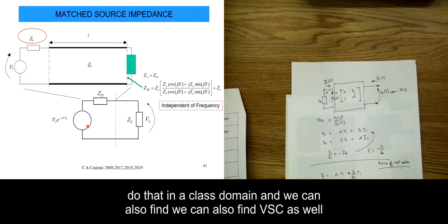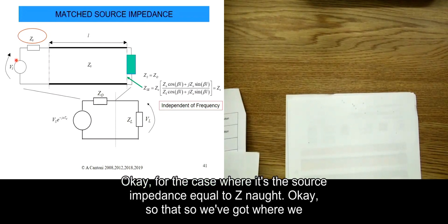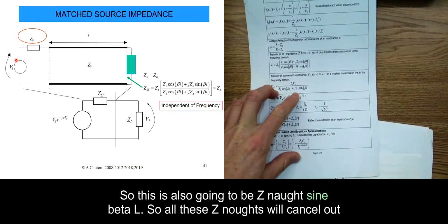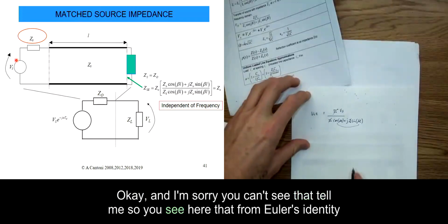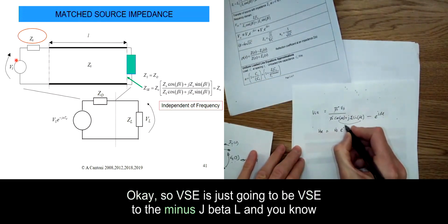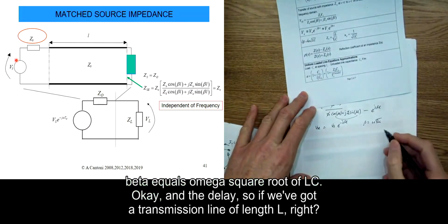You can also do that in the Laplace domain, and we can also find VSE for the case where the source impedance is equal to Z naught. So VSE equals Z naught VS on Z naught cos beta L plus j ZS sine beta L, and ZS is going to be Z naught, so all these Z naughts will cancel out. From Euler's identity, this is e to the j beta L. So VSE is just going to be VS e to the minus j beta L, and beta equals omega square root of LC.